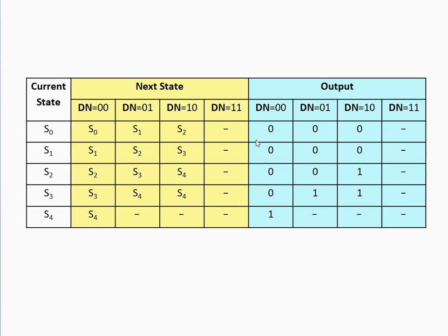And so we can then specify our algorithms for processing this information and coming up with a final design. The first thing we need to do is encode these states. We need to have binary combinations that encode these states.